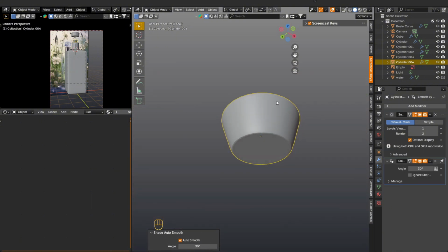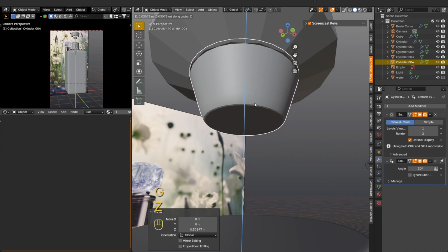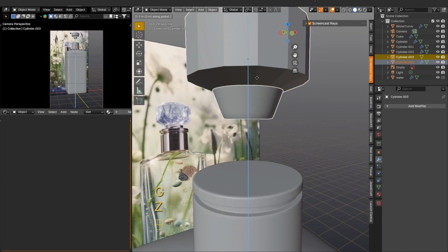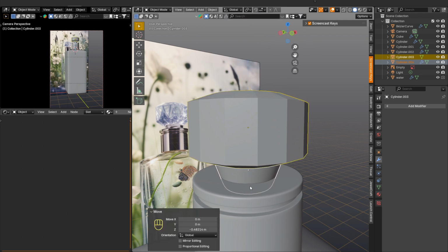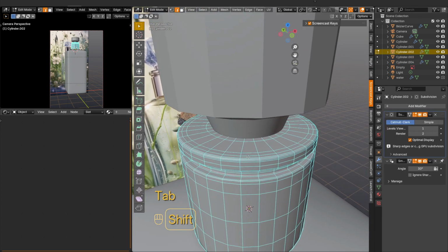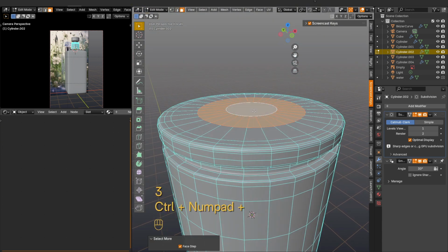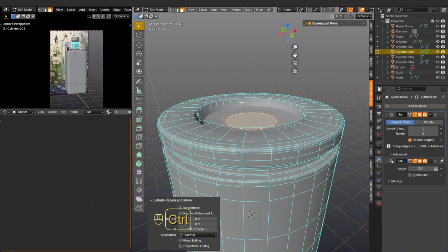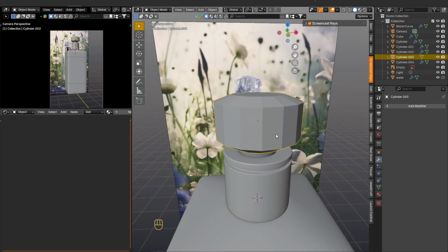And so now we are ready to combine the two objects that we have just created. And we need to join them with the third part of the cap. We pull these two objects down along the z-axis, so that they intersect with the third part. And now when they intersect, we see where we need to make a recess hole. We go into edit mode and extrude face down along the z-axis. Also do not forget to add edge loops to strengthen the topology.